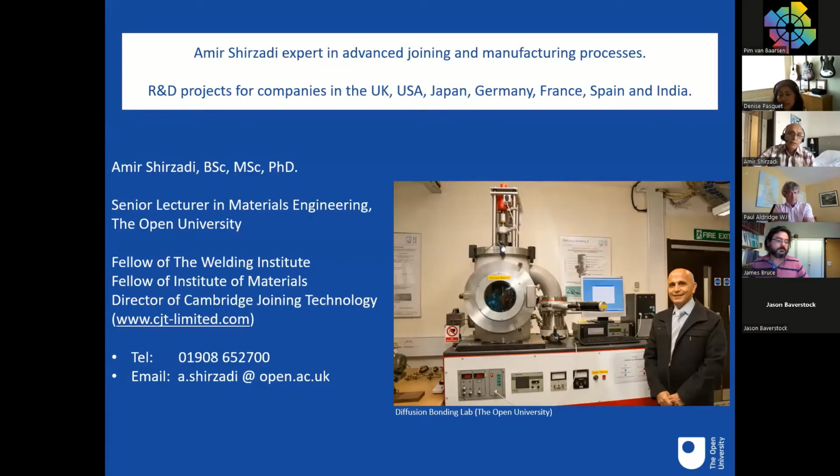The Open University is, to the best of my knowledge, the only university in the UK equipped with a diffusion bonding facility. We have several rigs, and the process of diffusion bonding is basically welding materials or joining them well below their melting point in order to maintain their original properties. I have done many projects with various companies around the world, which you will see in the next slide, please.